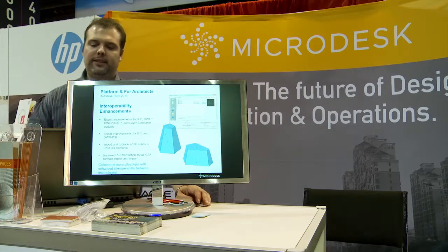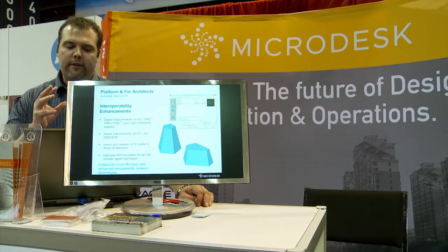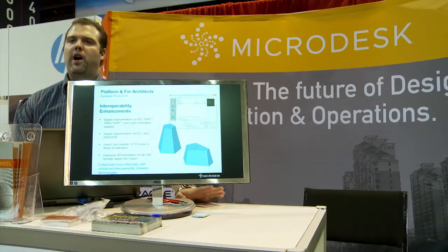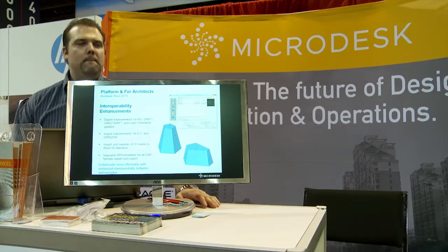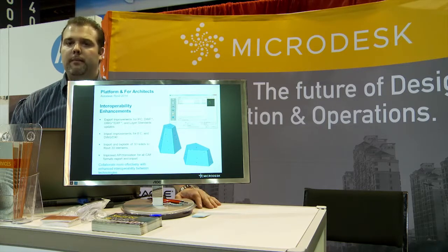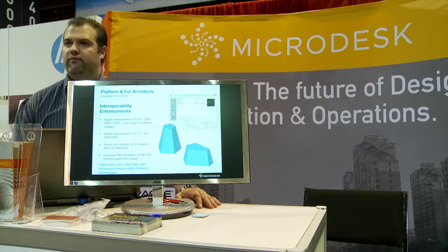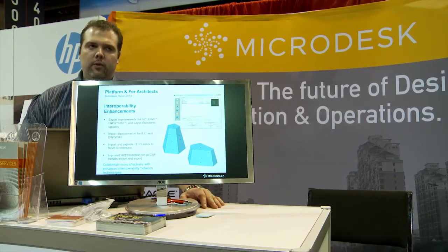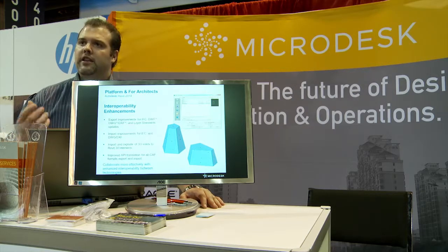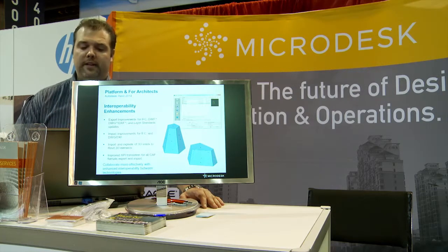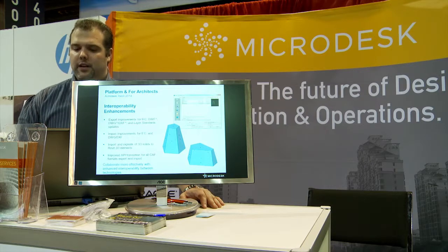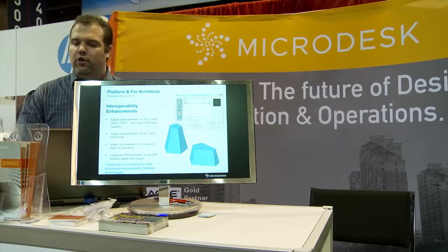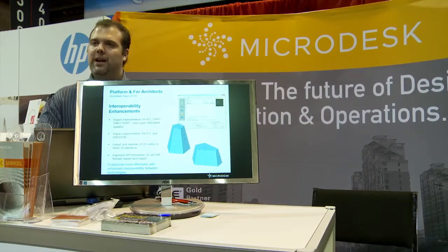Now, one that I think is my favorite is the ability to bring stuff from outside, break it up inside of Revit, and be able to manipulate it. To give you an example, how many people use the Google Warehouse for SketchUp models? Millions of models are available for free. You can use them for manufacturer specific, let's say Ethan Allen furniture. You want to bring it into Revit, create a family. In the past, it wasn't recommended, and it's still not recommended, to bring in geometry from outside of Revit and use it as it is. You have to go through some conversion process and flatten it out and use it for reference, but it's not recommended to use the geometry as it is.